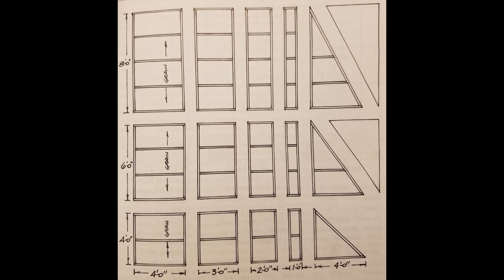and resistance to forces. If you were to use 1/4 inch or 1/2 inch plywood as the skin or the top layer for your frame, those sections in between the frames would be very brittle and weak. So over time, people stepping on them would basically cause it to crack, break, or punch holes through it. Versus 3/4 ply, which is the strongest type, allows pretty even dispersion of weight over a small distance.